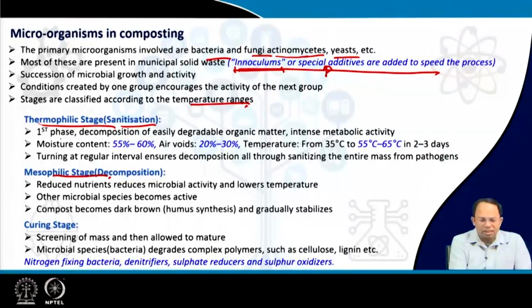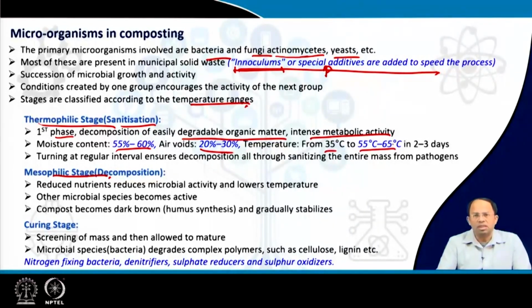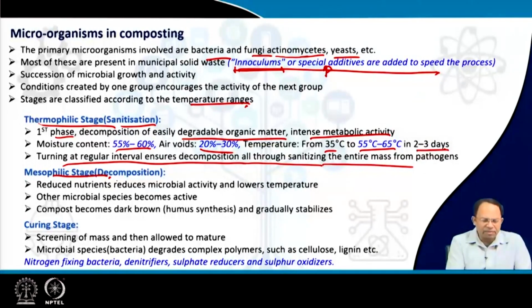So it's, as you know, the first phase: decomposition of easily degradable organic matter. Intense metabolic activity happens. Moisture content remains around 55 to 60%, air voids around 20 to 30%, and temperature rises from 35 to 55 or 65 degrees, and this remains for 2 to 3 days. And we have to turn at regular intervals so that it ensures decomposition all through and sanitizes the entire mass from the pathogen.